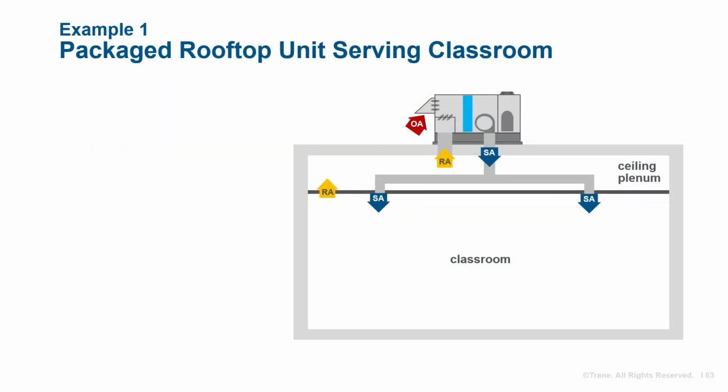This system is categorized as a high probability system because a portion of the refrigerant system, the evaporator, is located in the airstream, and a leak from this evaporator would result in refrigerant being dispersed into the occupied space by the supply airstream. This is an example of connected spaces via a ducted distribution system.